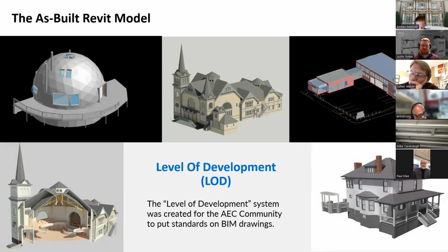When modeling as-built plans, LOD 200 is the most applicable range, since you are assessing a structure that has been built from the outside, with many interstitial spaces being inaccessible. The specific construction of many architectural and structural elements cannot be determined then, which is required for LOD 300 and above models.